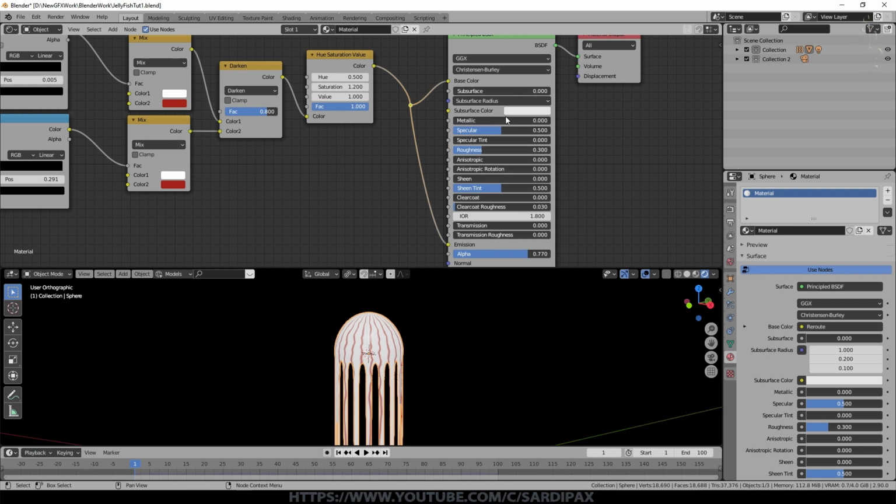And I set metallic up to about 0.122, so just giving it a slightly metallic effect. I put anisotropic up at 0.53. And I arrived at these values by just playing around with individual settings and seeing what it looked like. And transmission I set to 0.041. Probably didn't make a huge difference, but we'll see.